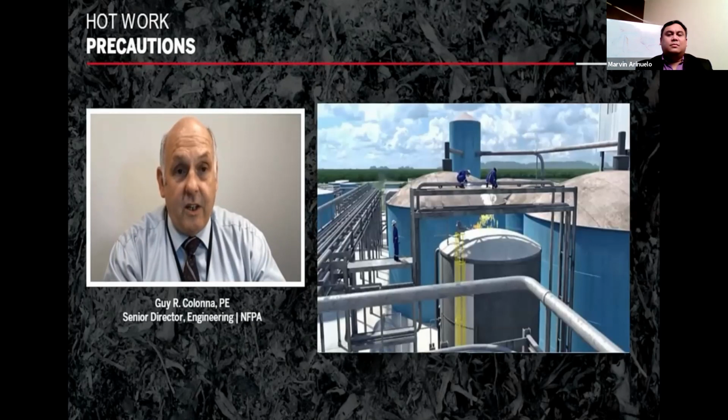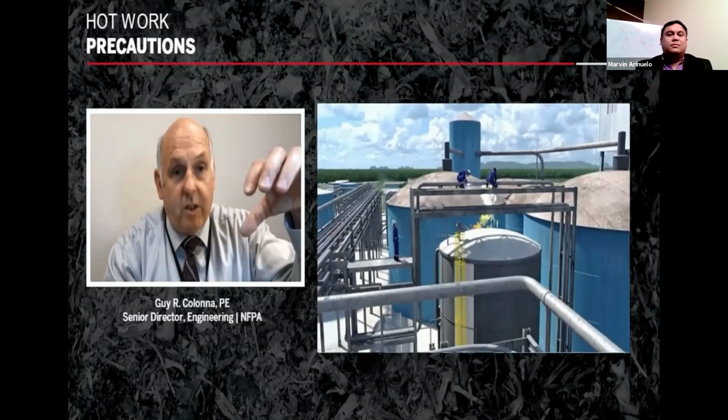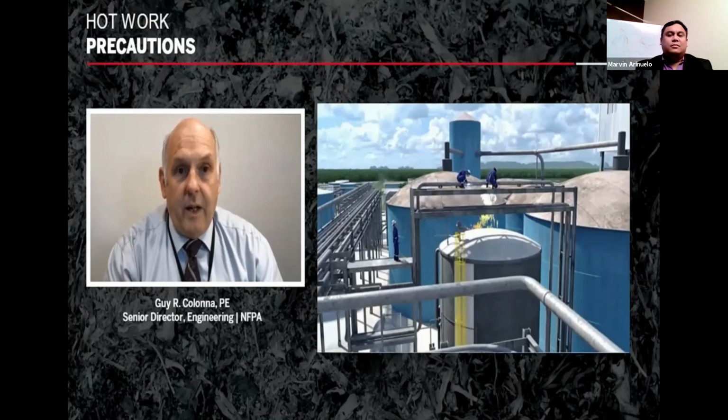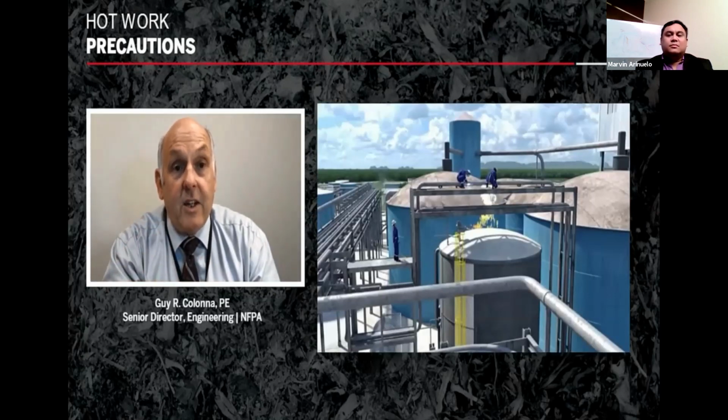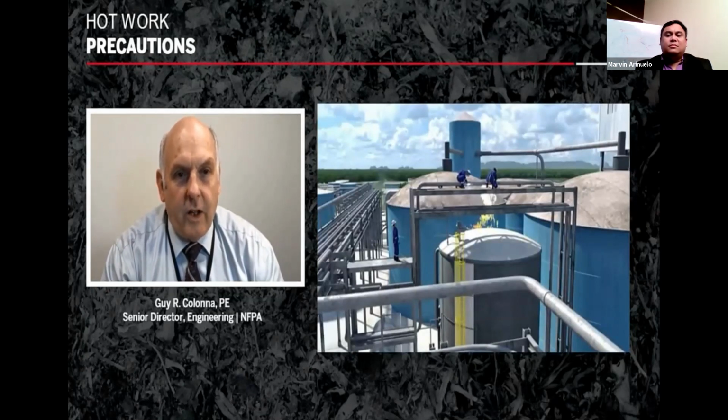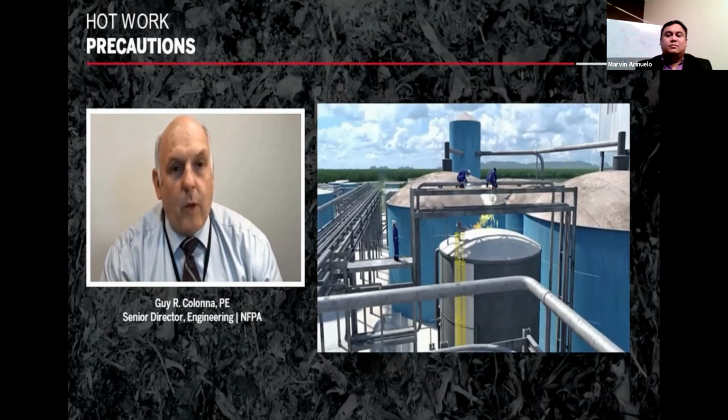And in this instance, as illustrated in the video, the work was above that tank where the likely gases and vapors were being emitted from in terms of evaporating and possibly bringing the ignition source from the falling sparks and slag into the area where the gases and vapors were present. So in terms of the hot work activities, what this video illustrates are some practices that are sound practices with respect to preparation leading up to the permit process.